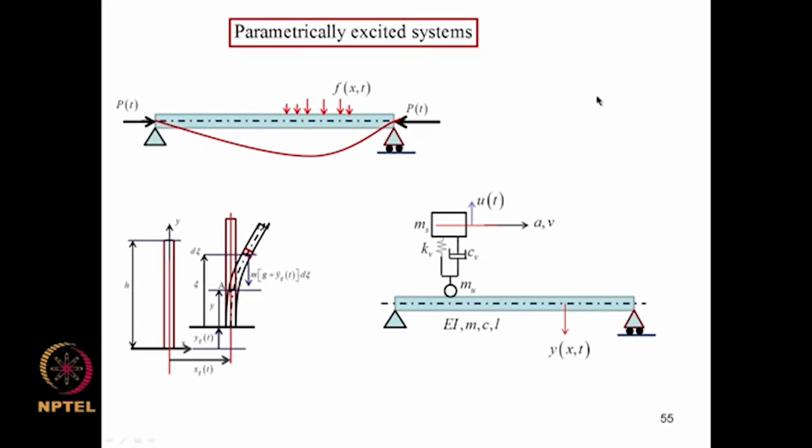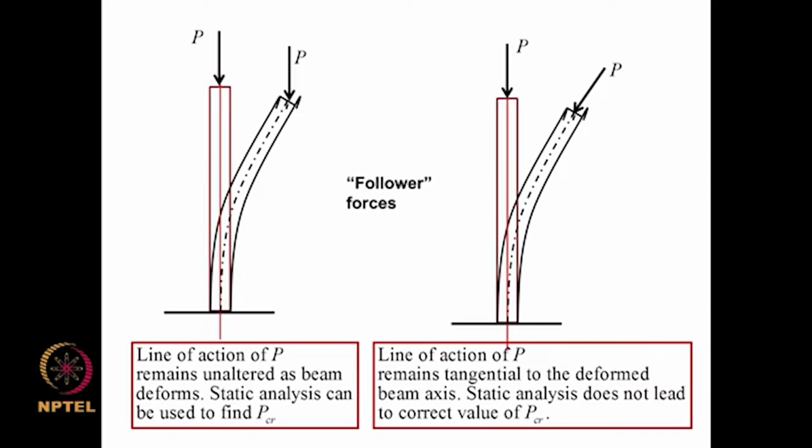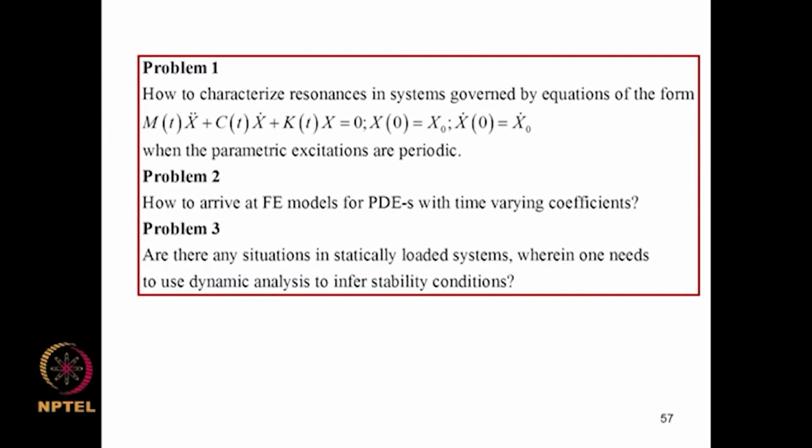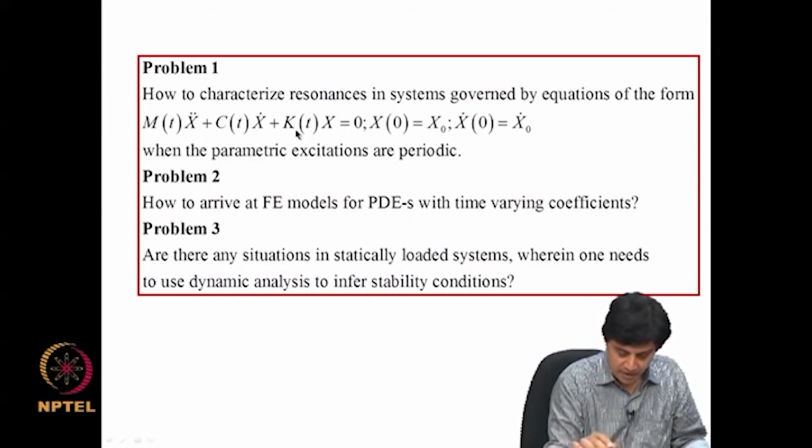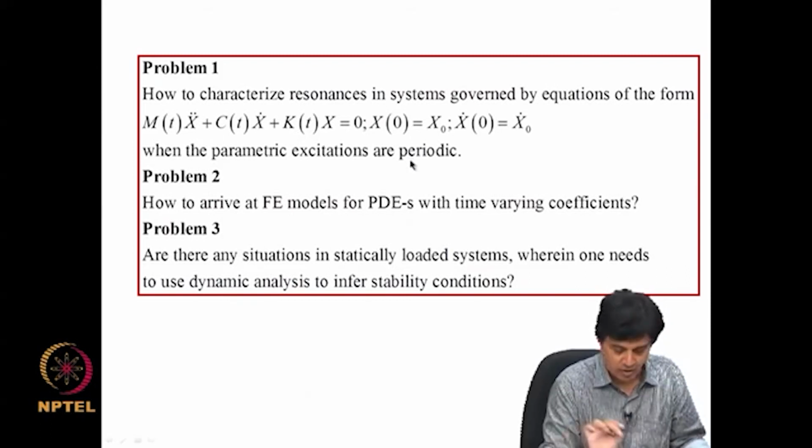So these 2 cases, parametrically excited systems and the so called follower force models, indicated situations under which a dynamic analysis needs to be done to infer stability of the system. Now in this context we considered 3 problems. First, how to characterize resonances in systems governed by equations of this form, where the mass, damping and stiffness matrices are time dependent, especially when these time variations are periodic.